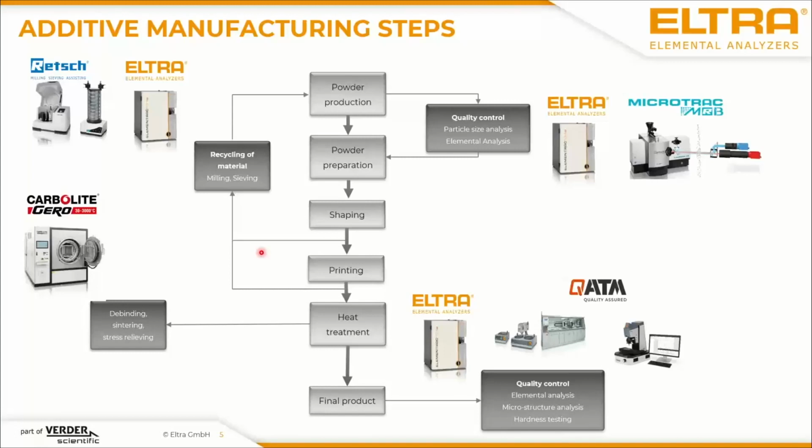Producers of 3D printing instruments give certain advice and recommendations how frequently such a powder can be reused, but of course by controlling quality by yourself in terms of elemental contaminations you have there, or in terms of shape and particle size, you might be able to use and recycle those powders more frequently, which is definitely an economical advantage. And of course, very important, you could see if the powder quality you're using there is already good for operation and for printing.